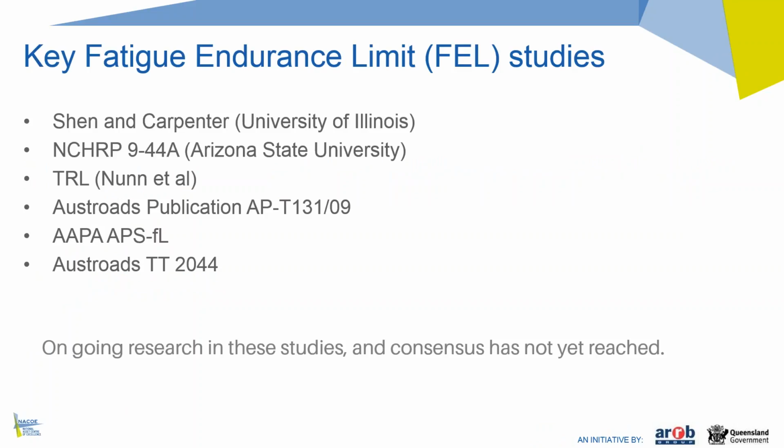But to give you a bit more background, currently asphalt thickness continues to increase with increasing traffic, and there are a lot of studies nationally and overseas which suggest that when the asphalt thickness reaches a certain point, continuing to add to it doesn't bring much benefit. This is what drives this whole process of putting a limiting traffic onto our pavement design in Queensland.